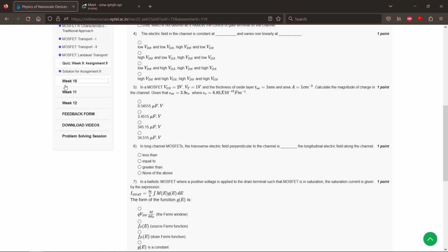To familiarize yourself with those things, you can maybe look at some quantum dot based devices, because the behavior of quantum dots is essentially quantum mechanical. Even when we apply an external control voltage through gate terminals and several configurations of gates, the behavior of the quantum dot device itself is always going to be quantum mechanical. That kind of language will be used for transistors also when we go below the ballistic regime. I hope that kind of answers your question.